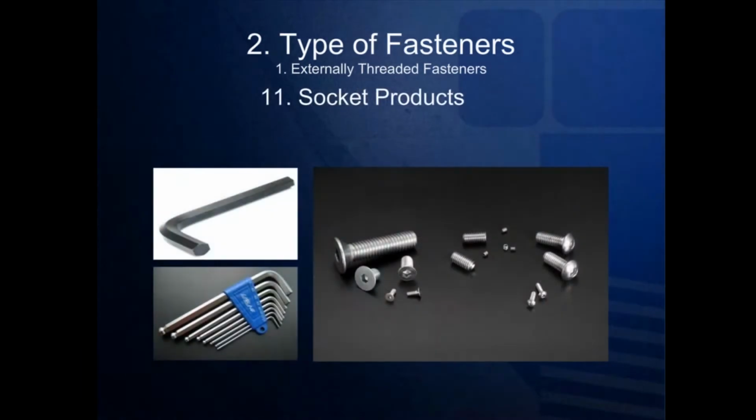Socket products is the next type of externally threaded fastener which we will cover. This group includes a large variety of products that share a common similarity in that they all have an indented hex known as a socket type drive. Most plain finish socket screws are actually made of an alloy steel that has similar mechanical characteristics or strengths to a grade 8 material. Therefore, the strength of a socket set screw or socket cap screw allows them to be better suited in holding machinery and industrial equipment together.